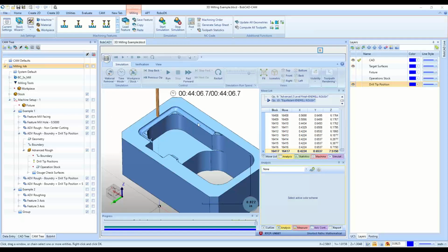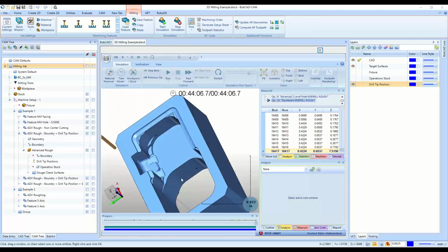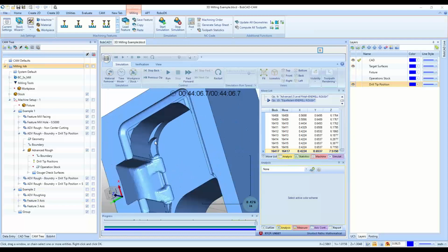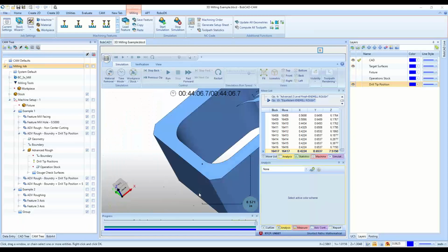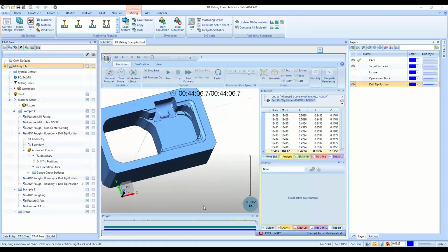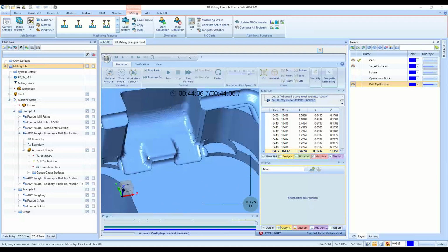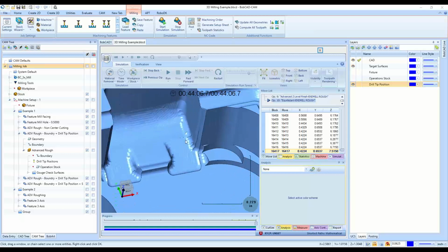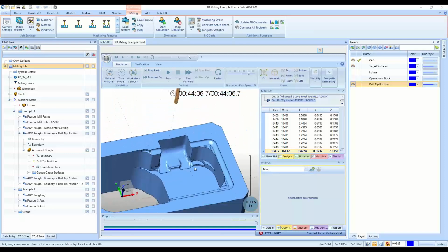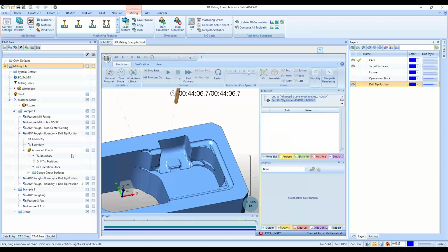By creating a solid model and using an extrude boss, this one looks like we could do a little more work on the corners there, but you can see here it's getting better with the semi-finish here. Getting into the corners, we just need to use a smaller tool next for this finish operation here and getting further down into it too.